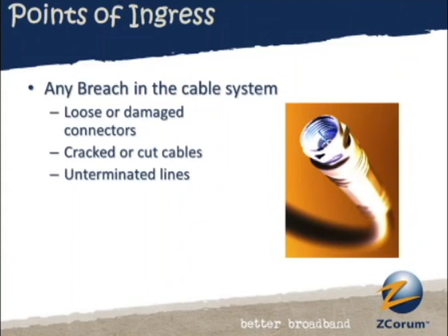So anywhere, I guess, where you've got a breach? Yeah, and again, none of this information is going to be unfamiliar to people who've worked in cable before, because these are all problems that we've dealt with, and in some cases kind of shook our heads and not dealt with. But any place you have damage to the physical cable plant is going to allow signal both to come into the plant as well as to leak out of the plant. So ingress and egress go hand in hand. They're two sides of the same coin. And in almost all cases where you have a source of ingress noise, you also have egress noise, and vice versa.